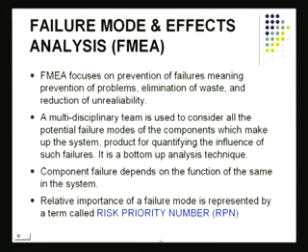The bottom line is going to be again calculation of the RPN. This is something we'd like to be able to do. We'd like to work out the components of the RPN. Again, the risk priority number is made up of the severity, there'll be a rating, a number for the probability of the event taking place, and the detection capability. These three things must come together, and if they give you a high RPN, that's a serious matter. You've got to take some corrective action. And these numbers come out as the result of this FMEA analysis.